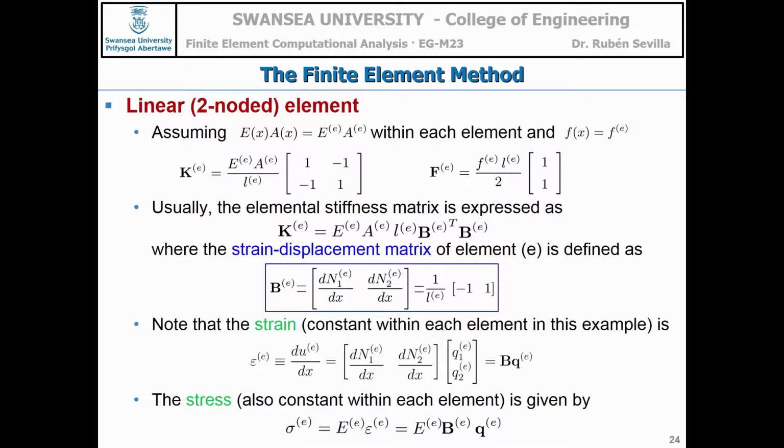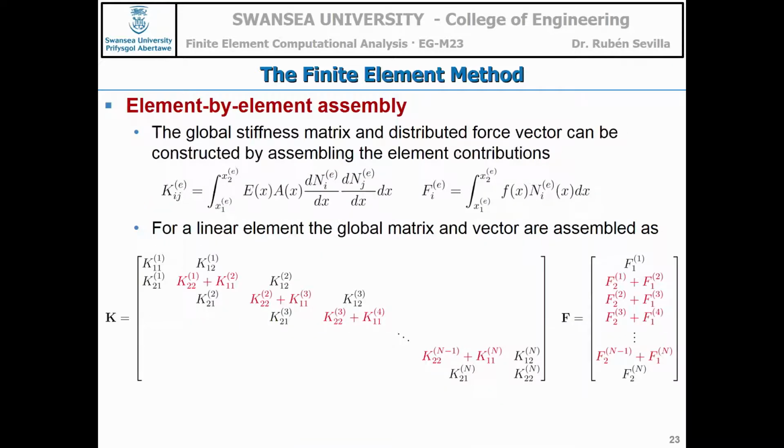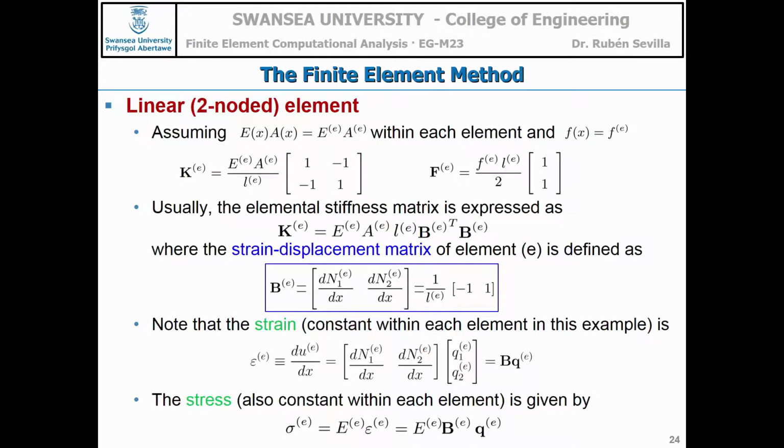Right? Question, quick one, to see if you're following. Do I need the force to be constant across the whole bar in order to be able to apply these formulas? Is that what I'm saying? When I say here that in order to take f out of the integral I need a constant external force, is this across the whole bar? If not, just in the element. Important: you can have different forces in different areas, and this is still valid. So it's a limitation, but make sure that you understand it.